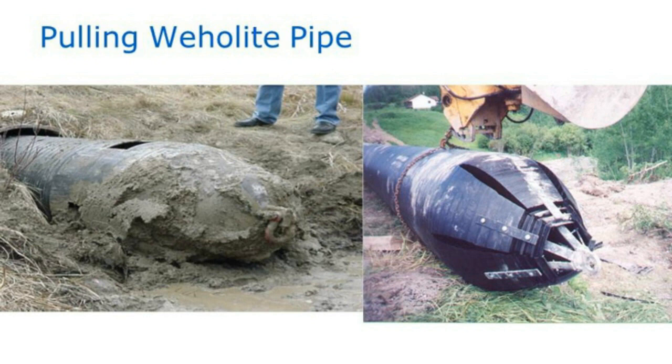Now, one note to make: if a pulling head is required, that will have to be determined prior to construction and going to the job site. That's a sacrificial piece of pipe. So for whatever length the contractor decides that he is going to do that, we're going to have to add that to the length of the run of the culvert.